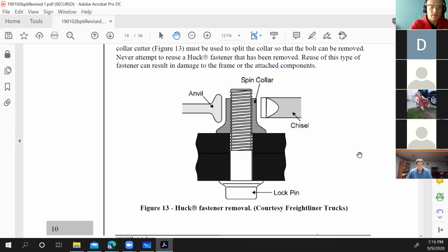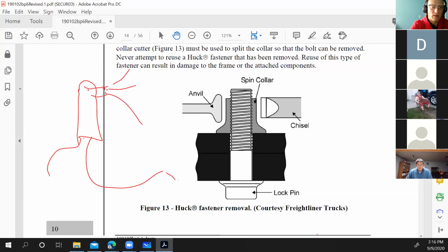So the air arc, it essentially looks like you're stick welding, right? You have a stinger with the cord. There's going to be another air line on here and then an air nozzle. So air is blasting out from here, and then you have a large carbon rod. Wherever you strike that carbon rod, it just burns the steel away and blows slag all over the place.